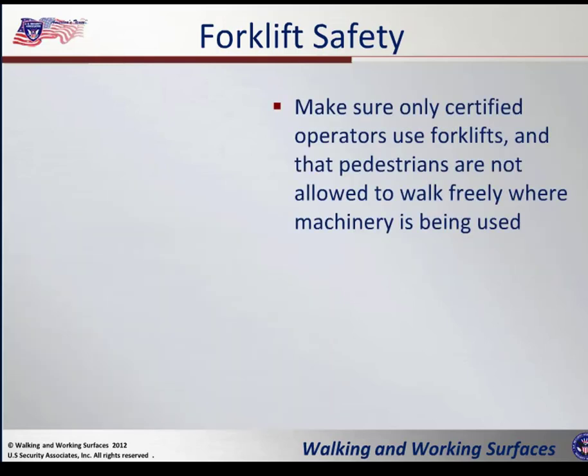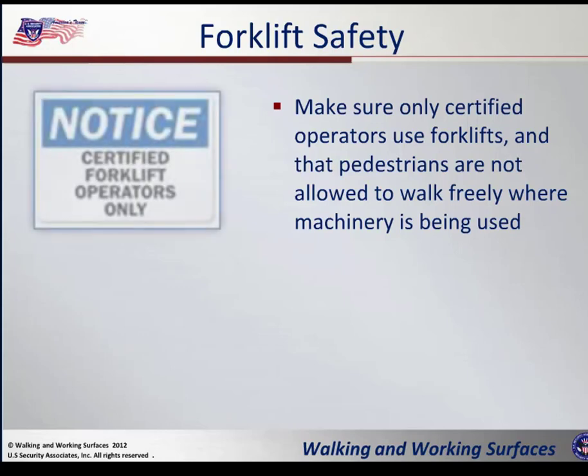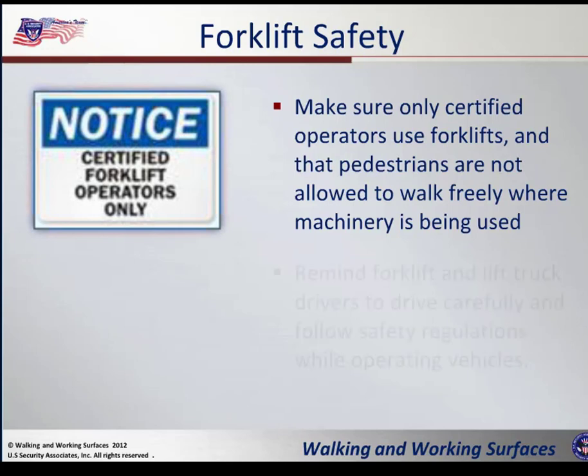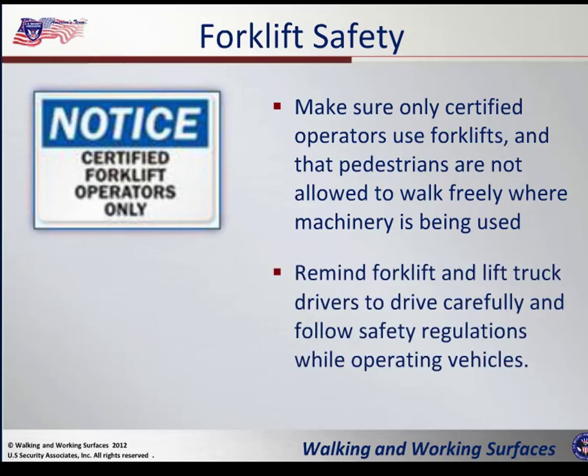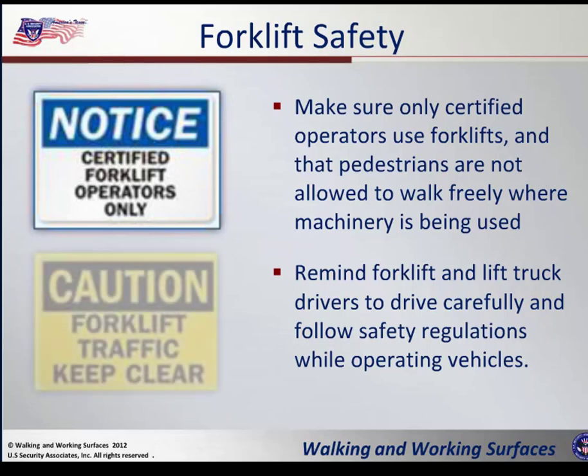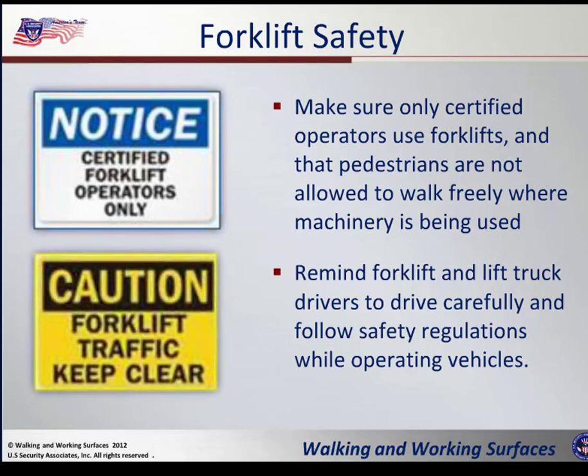Now, when you're out there doing your patrol, if you see somebody operating a forklift, what can you do? Well, one, you can make sure that only certified operators use that forklift and that there are no pedestrians around who are allowed to walk around freely where that machinery is actually being used. Also, remind the forklift drivers to drive carefully and follow the safety regulations while they are operating that vehicle.